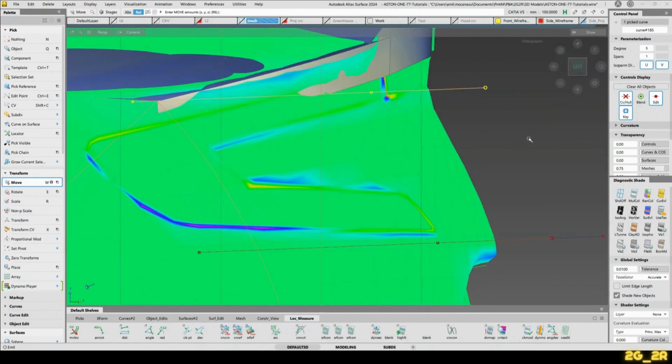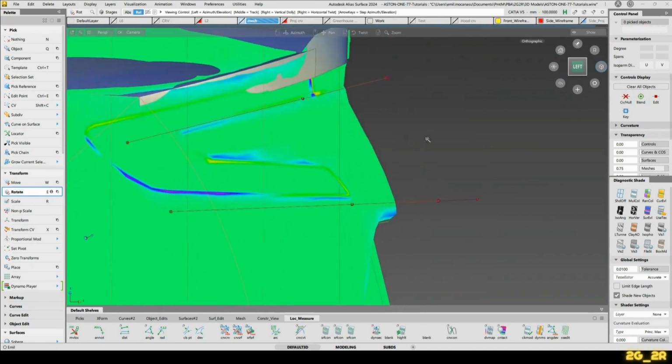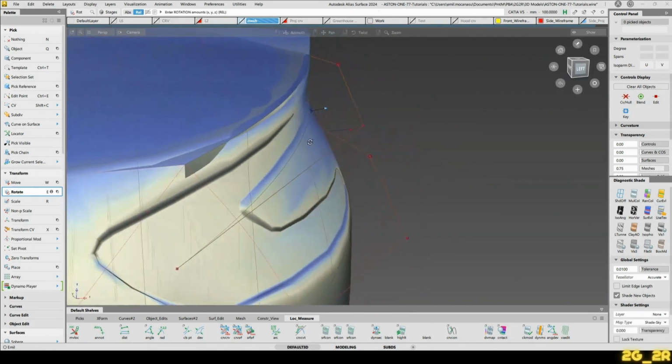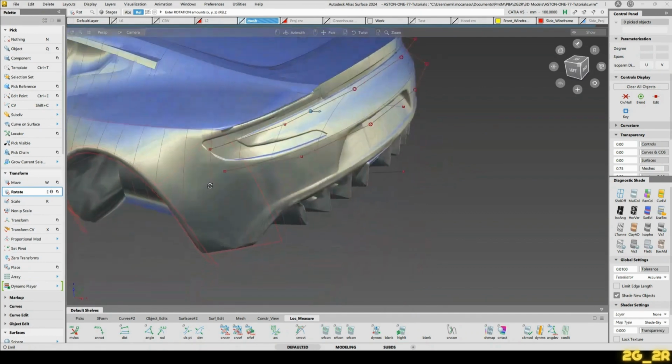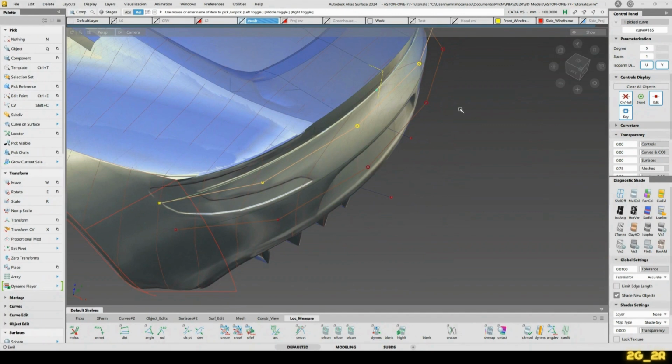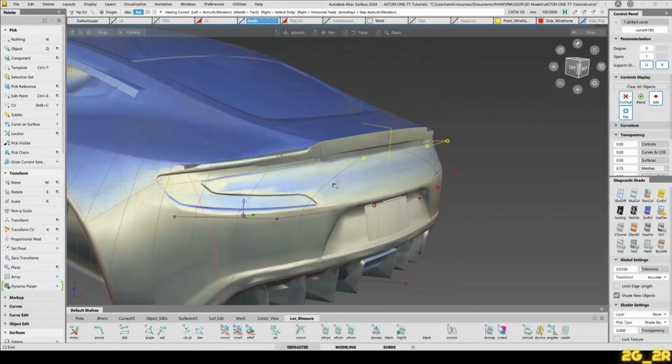And then we rotate the curve. Something like that. Yes. Let's shade this again, different shader. Pretty good. We can take that curve and non-proportional scale it in the Y direction so we get closer to the mesh. That should do it.